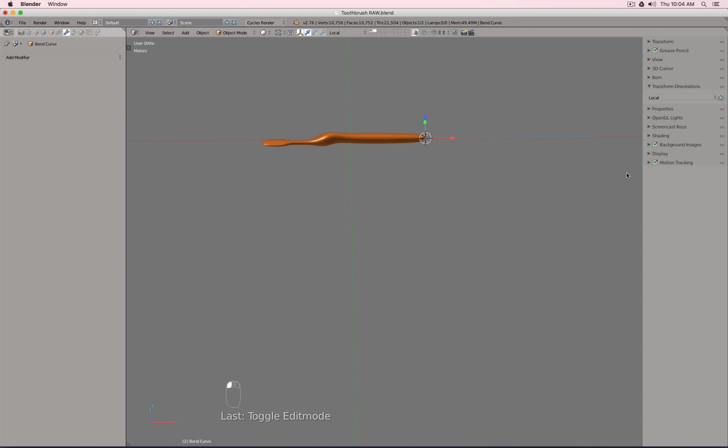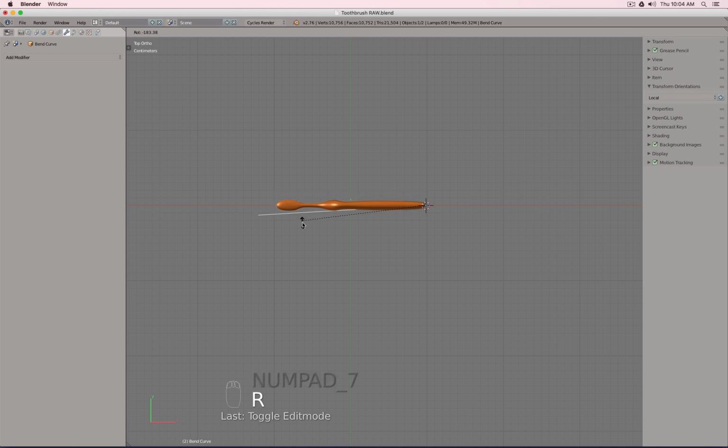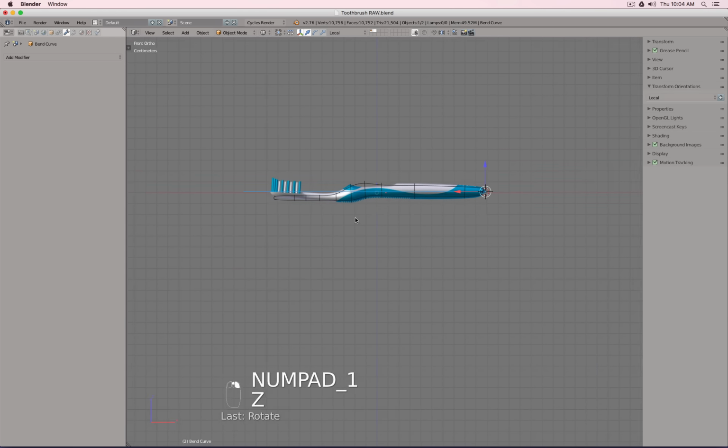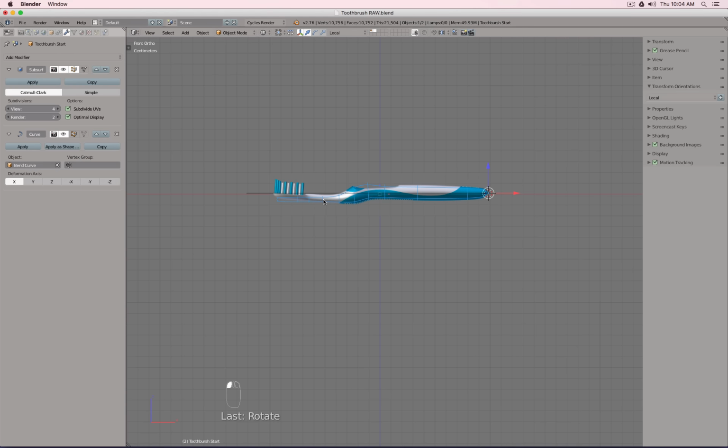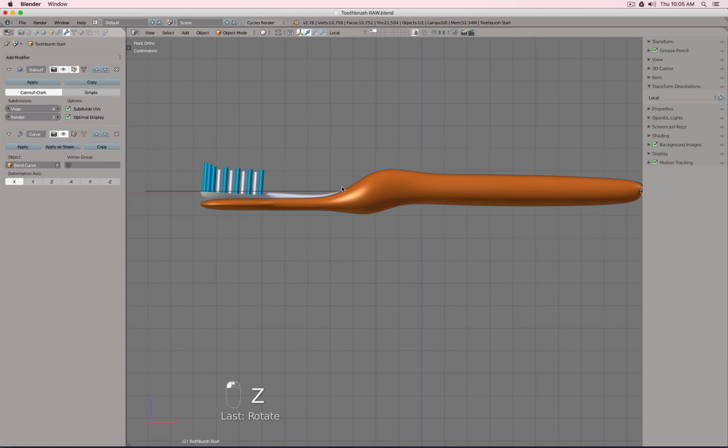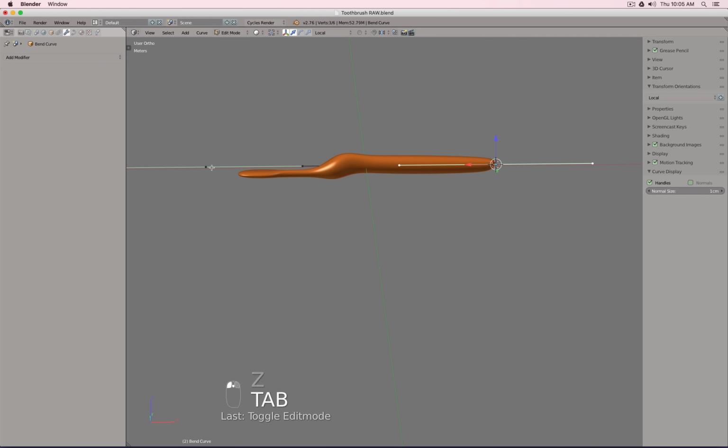Well, it's pretty simple. We go into top view and then we just rotate this one 180 degrees, because then you see now with local, positive x is this way and this object grows this way. And now if we, for example, turn this one on and off, you see nothing really happens. So what's all this for? Now you will see. So we can go into edit mode, and if I move this point left and right, a little bit happens.